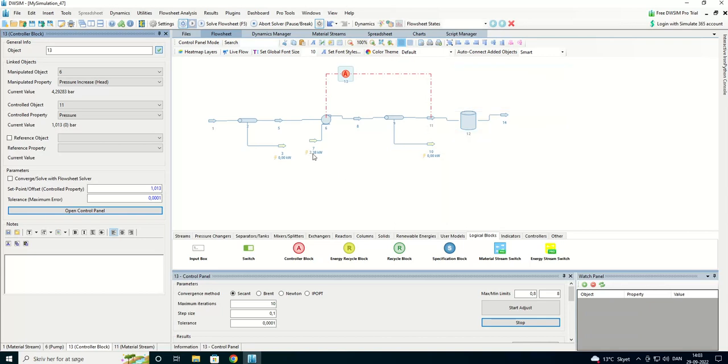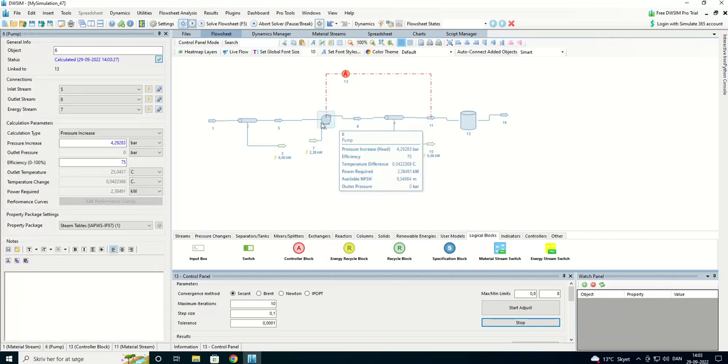We can see we're going to use 2.38 kilowatts for our pump with an efficiency of 75%. We have an NPSH of about 9.35 meters. We could just try to change to 60% in efficiency. And we can see we are going up to almost 3 kilowatts.